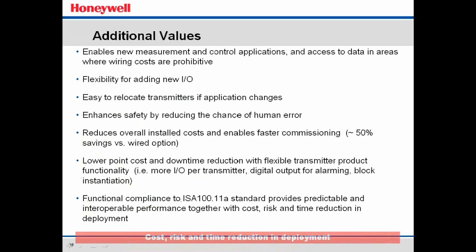Because I can clearly define that, because I have a stable, properly built-out network that's supporting those 1-second update rate transmitters or those control-based transmitters. So I know exactly how long it's going to take. I don't have to worry about it going from transmitter to transmitter to transmitter, where latency is all over the board. It's much, much longer, and you can't define it. It can take different amounts of time depending on the load on the network.